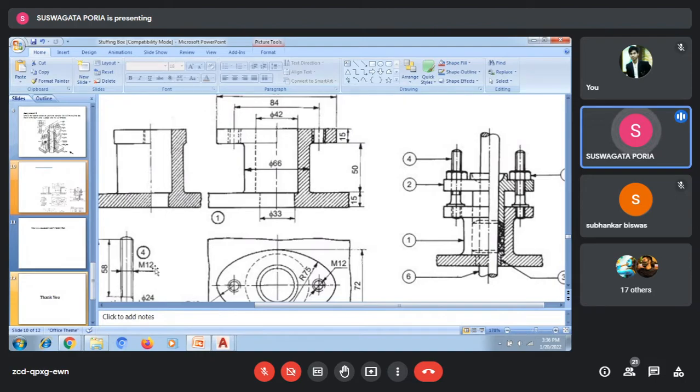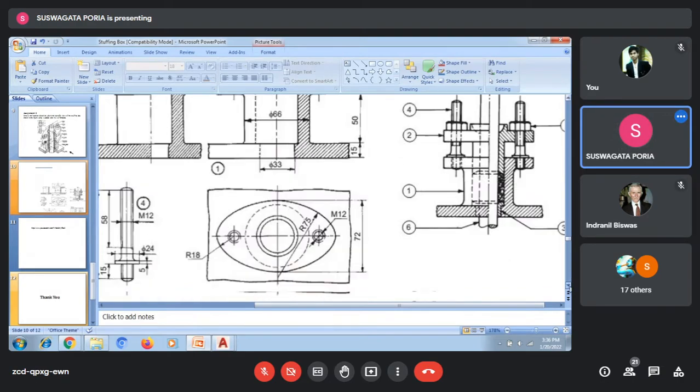So here major dia is 12. Okay, we will not consider anything. But when major dia 12 will go inside it, then there should already be a hole. And from where will we get that hole dia? We will get that from here.